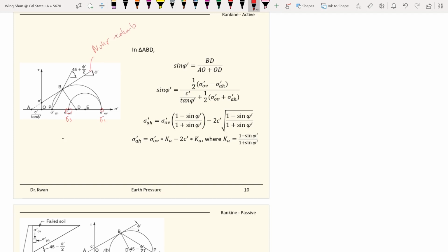We talked about all this in 366. So this is the Mohr Coulomb failure envelope. That's why from at rest conditions, your circle is growing larger and larger toward the active conditions, which means a smaller sigma 3, until a point that, again, this is kind of an evolving Mohr circle, right?